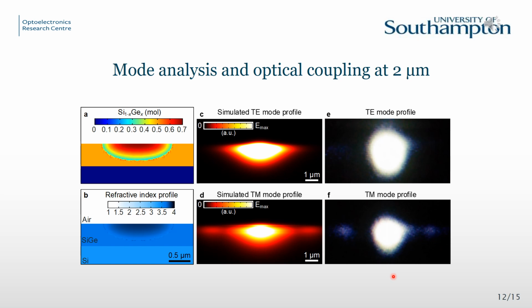Moreover, optical guiding was observed even for the waveguide written at the lowest scan speed of 0.1 mm per second, where the least compositional separation of silicon and germanium occurs within the laser processed region. Therefore, we incorporated the photoelastic effects, which are strain-induced changes in refractive index. We found that an increase of 3% in the refractive index within the laser processed strain region gives the best agreement with the optical experiments in terms of matching the mode profiles.